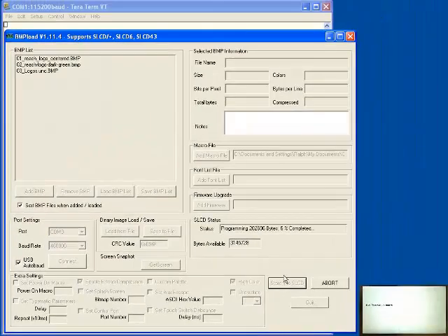When you're downloading bitmaps, macros, and fonts to the display module, be aware that all of these files are downloaded as a single package, and it overwrites anything that's currently loaded, so you need to keep specifying everything that you want in one package.